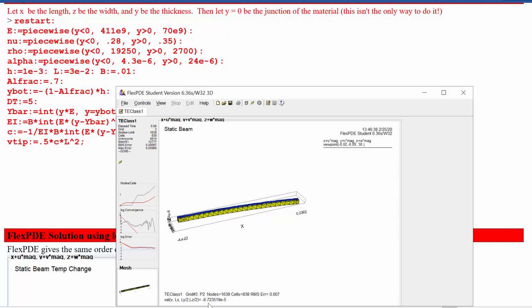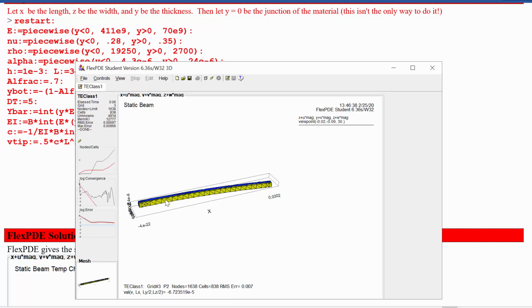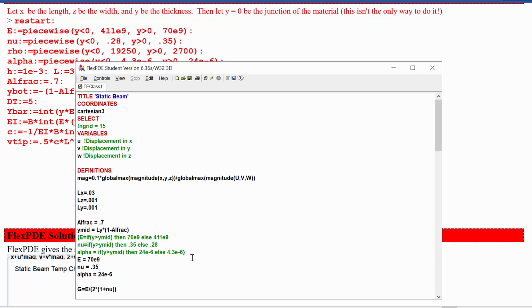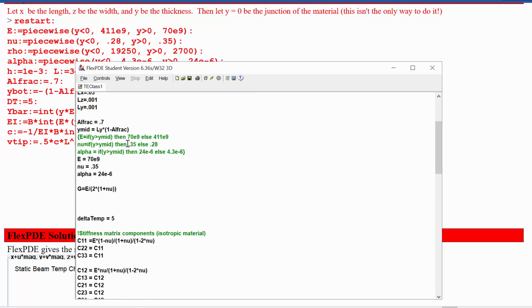Okay, so right away, a lot better, a lot closer to the 66 microns. Still would perhaps be better if we could do this simulation in even better detail. And a way to do that is to say, well, since this Z direction, there's nothing going on in it anyway, maybe we ought to improve the performance by completely eliminating the Z direction. So let's try that. Let's convert this to a two-dimensional problem. How could we do that?